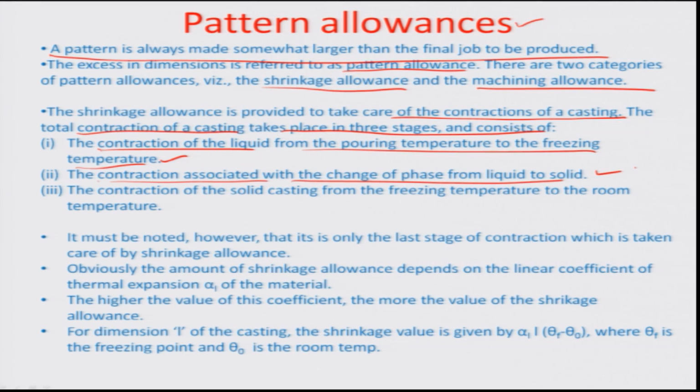And the contraction of solid casting from the freezing temperature to the room temperature is another aspect, where we are talking about the solid phase contraction. This is the phase change contraction, and this particular one is the liquid contraction prior to pouring.